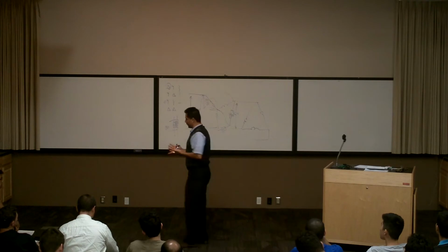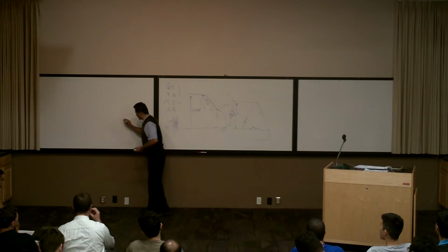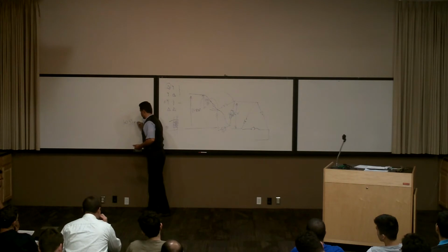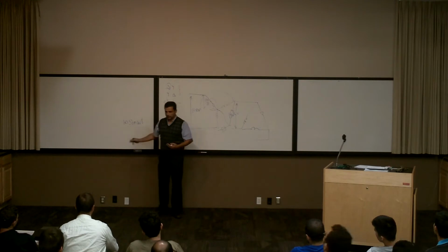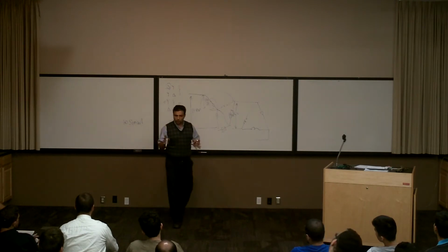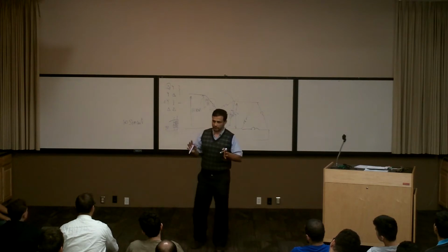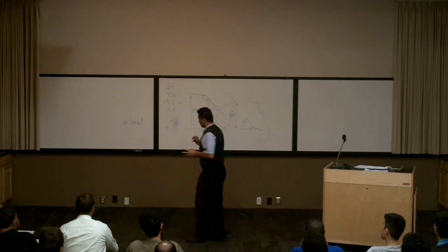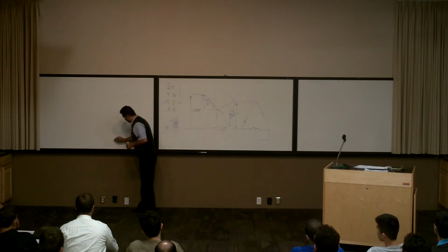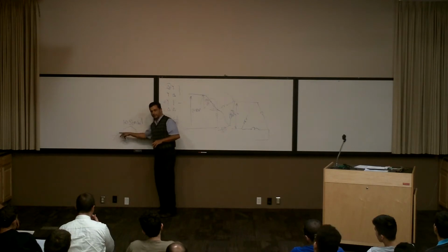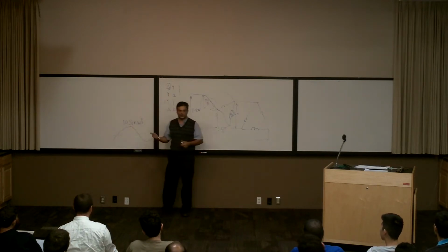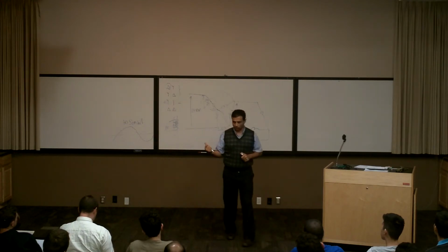An ideal source, for example an ideal generator, is going to generate a sine waveform, 10 sine of omega t. This is an AC generator, generating a voltage like this when it's rotating. This is ideal. But all generators, when they generate voltage, generate some harmonics. If you look at the voltage, it's not this bad, but it's something like this, like steps. It goes on. There are some harmonics in the voltage.